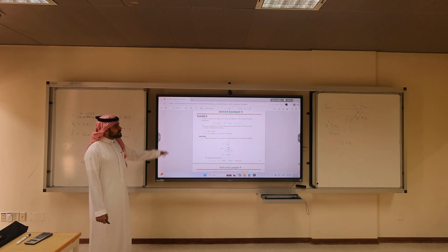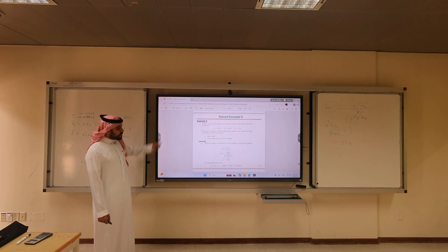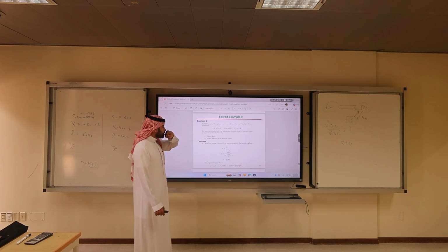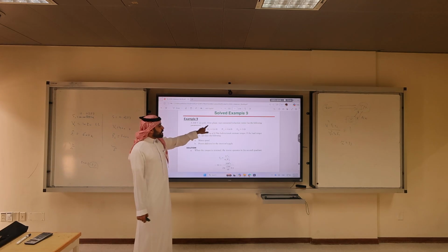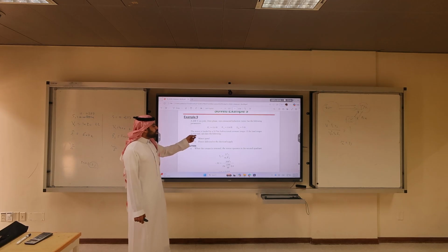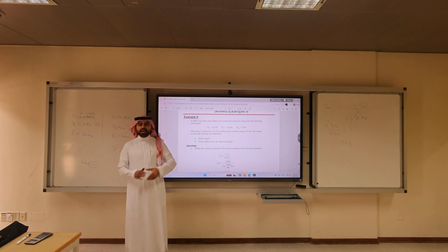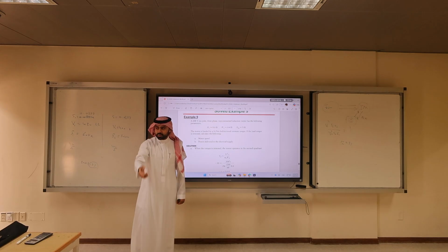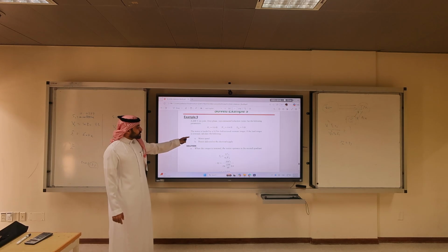So let's look at this example. Because this is deep technical, I'm going to solve this easy example now. We will go back later to the wind. This is a simple example: a 208 V, 6-pole, 3-phase motor, R1, R2 equivalent are given. The motor is loaded by 30 Newton meter bi-directional constant torque. So when the car is going up it is 30. The moment it goes down, it applies negative 30 on the load. It reverses the direction. If the load torque is reversed, calculate the motor speed.